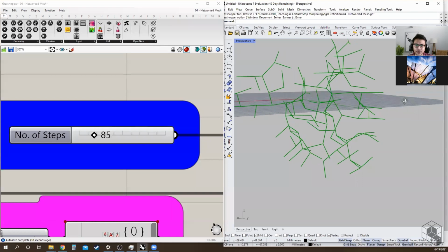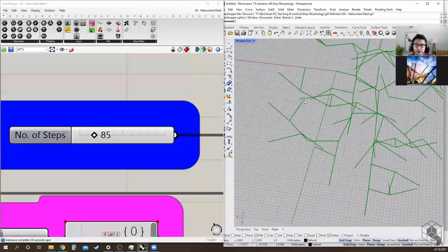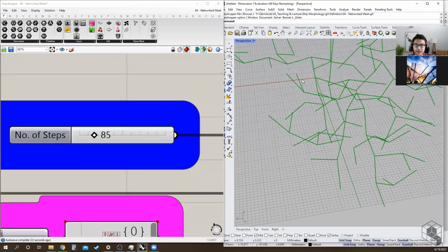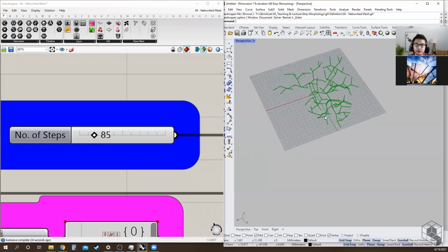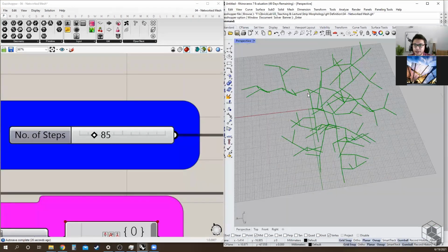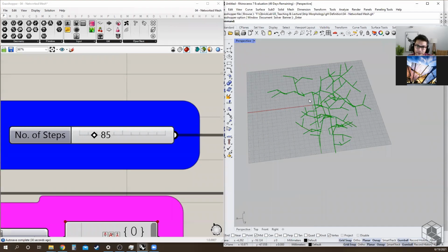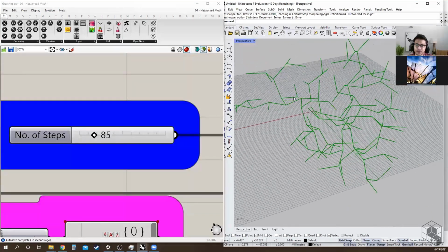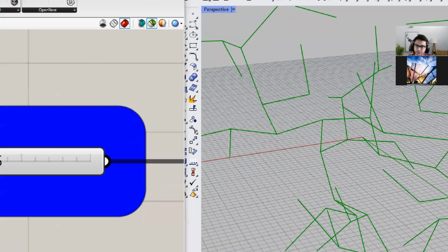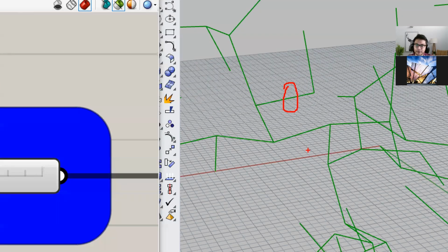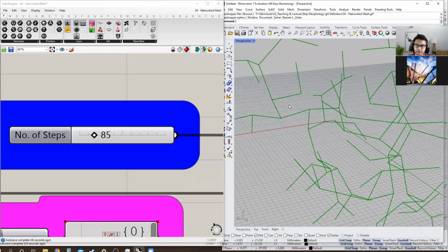And the second criteria is that the distance between any of these lines on the screen will be greater than twice the radius of the pipe that we are going to be wrapping this with. So if you're going to wrap this with a pipe, we need to ensure that the distance between the two is greater than their individual radius, so that it doesn't intersect.